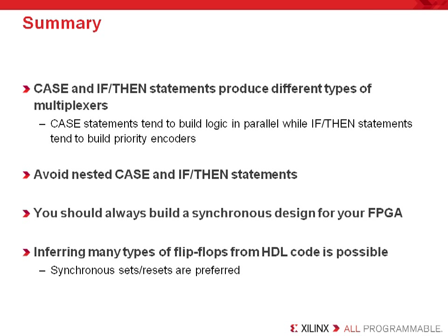You should always build a synchronous design for your FPGA, not just for speed, but the key thing here is to save you time and make your design more productive. And we mentioned a couple key tips about following good synchronous design practices. Build with your clock enable and use synchronous sets and resets whenever possible. Never build asynchronous sets or resets. Lastly, inferring many types of flip-flops from your HDL code is possible. And as we mentioned, those synchronous sets and resets are preferred.